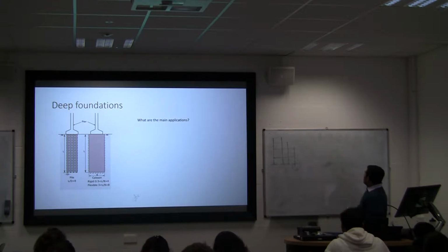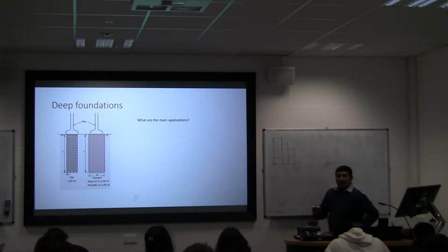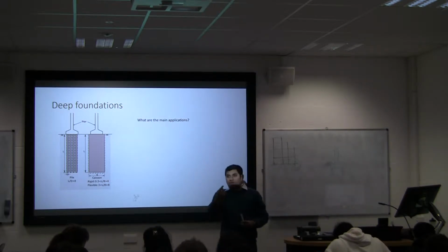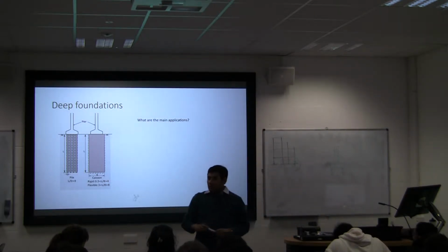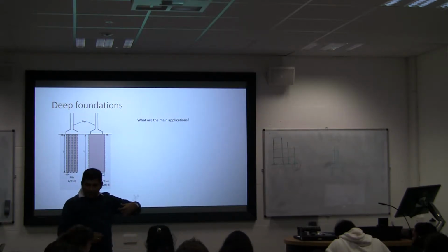So typically what is done, at a pile cap, the column bars will come down like that. The column bars have to come down and have a lap length there. The pile reinforcement has to go up as well. So if you want to have fixity, you have to do all the detailing like that. The column reinforcement has to go up. That's been made sure, right? So they are the reinforcements.